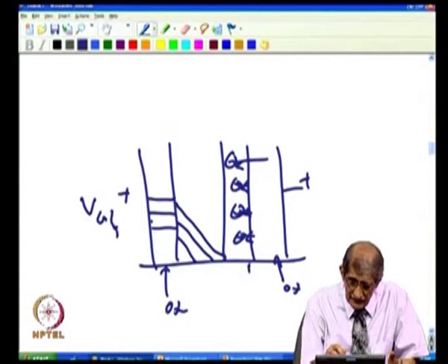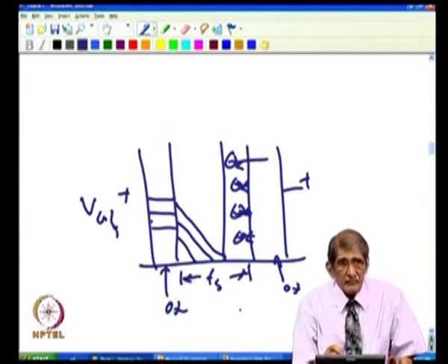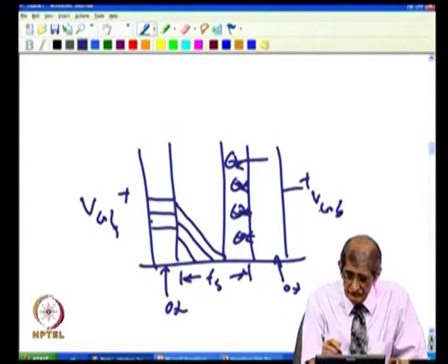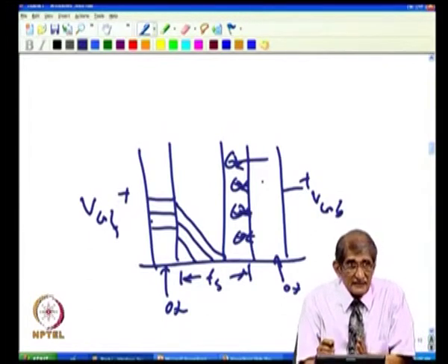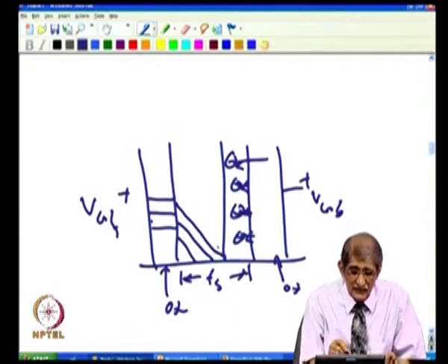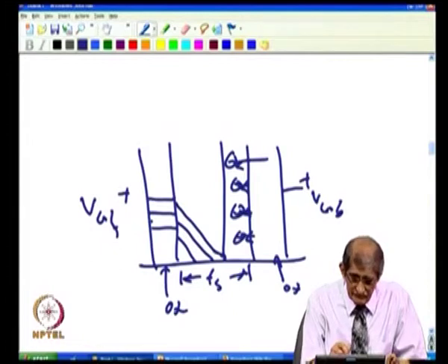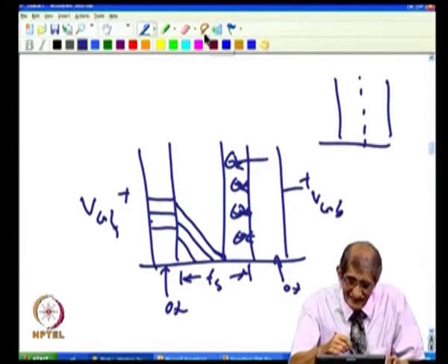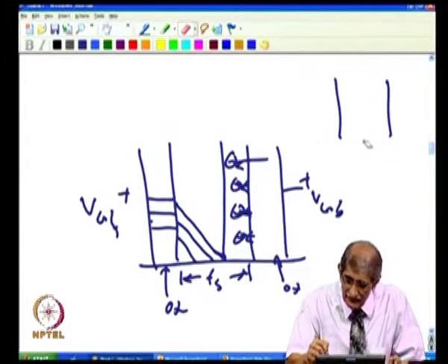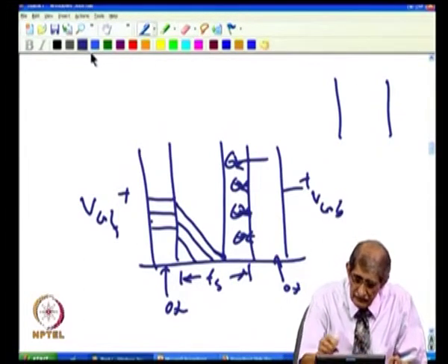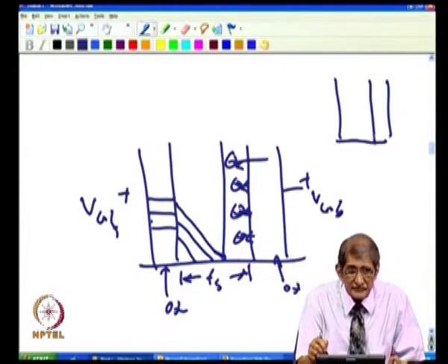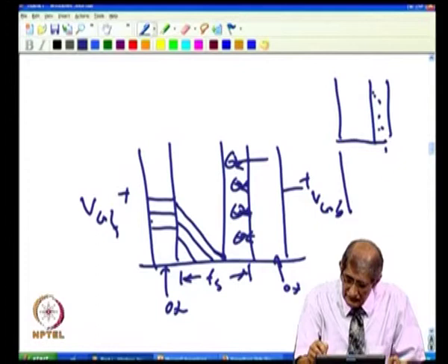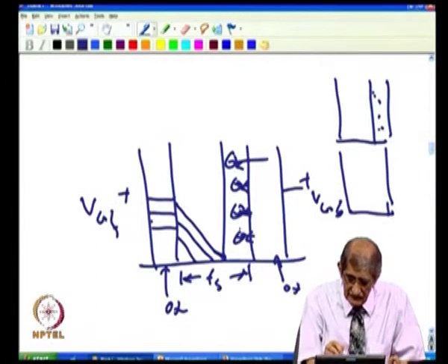Now, at this point, you see this is the T silicon. Part of this T silicon, the depletion layer has been occupied by this back gate VGB. This has been taken over by that. You have fixed that. Now, when I have applied up to this point, you have got 0 field here, because if you plot these electric field lines from the left hand side and right hand side, if you draw that was the depletion layer, which is already occupied by the back channel. Now, if I take the electric field now, how is it? Only here in the channel region, T of S.